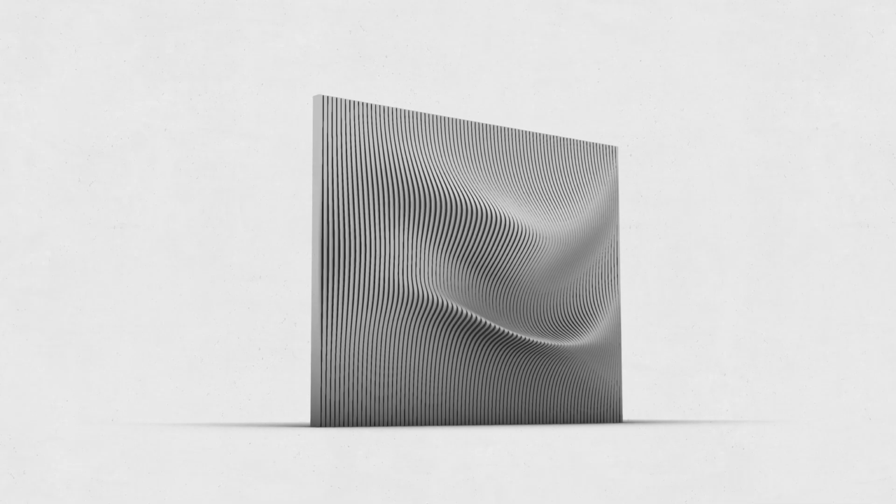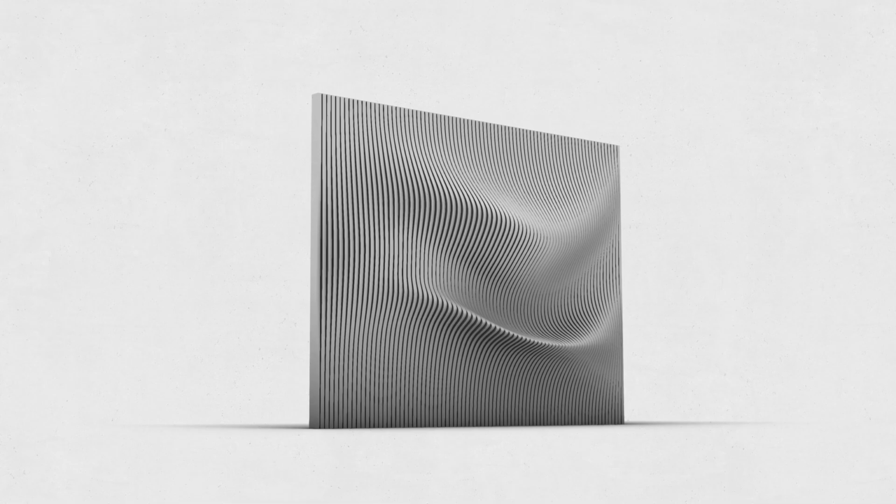So for now, let's totally ignore the whole mesh or contoured parts. If you really take a good look, what we've got here is a wavy surface, and in some spots it's even created little areas where you can sit. So the first step is to model this surface, right? There are various ways to create this shape, but for this exercise I want to use Loft. If you guys know any other methods, just drop them in the comments, okay?